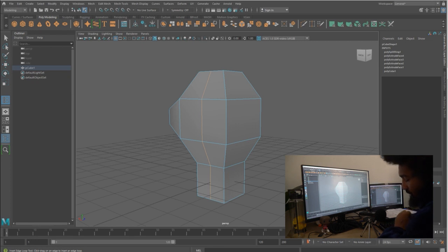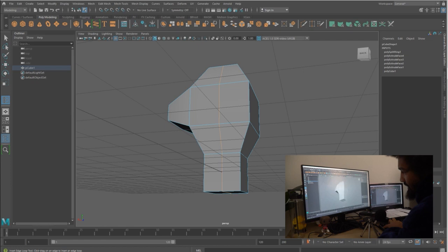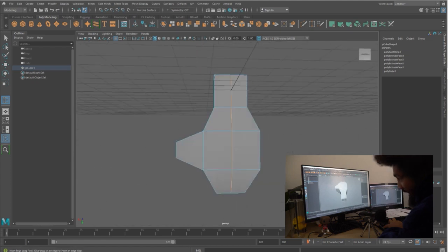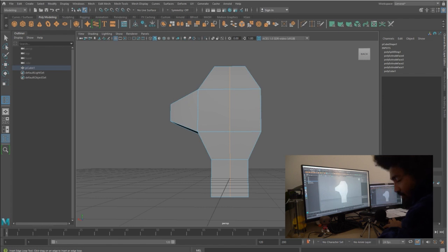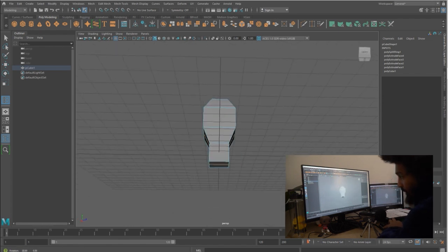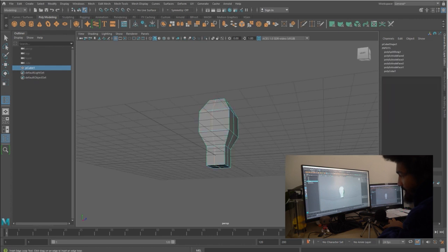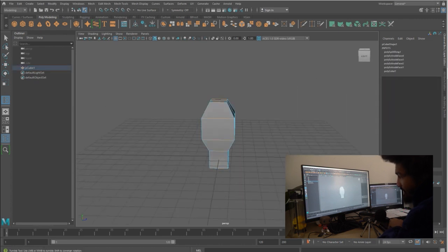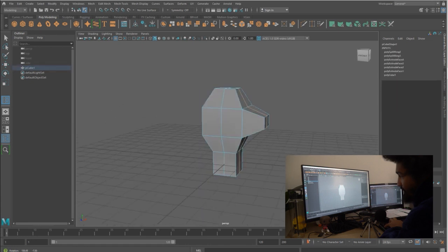Why a loop? Because if you see on the animation, what's happening is you want to make sure you still have faces of 4. So this edge loop means you can basically make a line splitting this and still have always 4. So you're dividing everything by 2 on those faces. Like here you can do it as well, and you're going to split here as you see. So this is without, and you see it's going to split all these faces in 2.